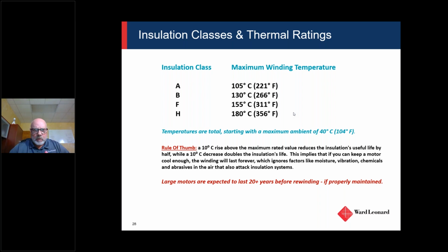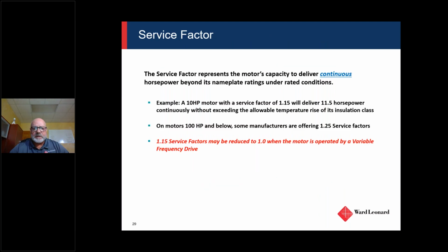And that's important. If you're running into a service factor, that insulation class rating is going to be critically important. Honestly, what the service factor really means, and I'll just read it, is the motor's capacity to deliver continuous horsepower beyond its nameplate ratings under rated conditions, right?